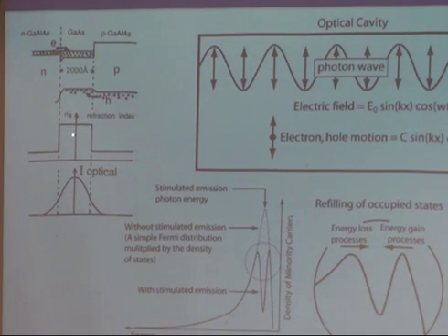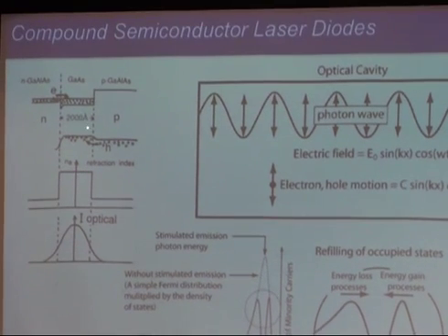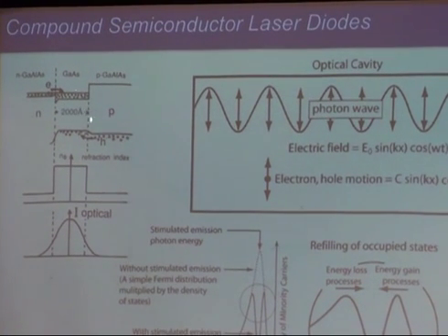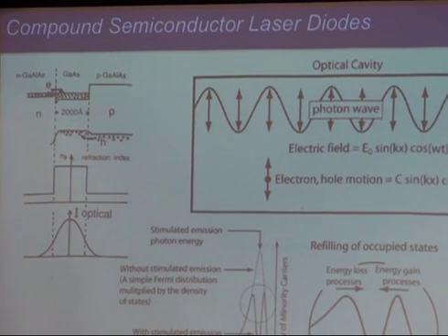But there's a very interesting trade-off, because the light is being generated right here in this region, and there are a lot of carriers here. One of the very big loss mechanisms is what's called free carrier absorption. If you have too many free carriers, they can absorb; they get kicked up to higher places in the bands and all that. And you want to avoid that. So you want the light tail to be very high outside, not inside here. So that's the design typically people use.